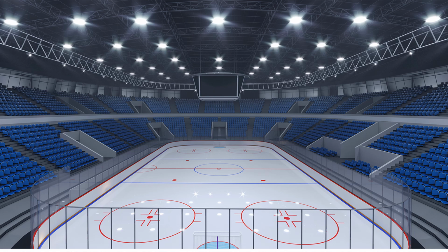High CRI lighting, typically above 80, is preferred for indoor sports to ensure accurate color reproduction, both for the participants and the audience. Sports facilities use significant amounts of energy for lighting, especially in large arenas or stadiums. Therefore, energy efficient lighting systems should be prioritized. LED, or light emitting diode technology, is commonly used in modern sports facilities because it consumes less energy, has a longer lifespan, and provides instant brightness without the flicker associated with older technologies like the fluorescent bulb.